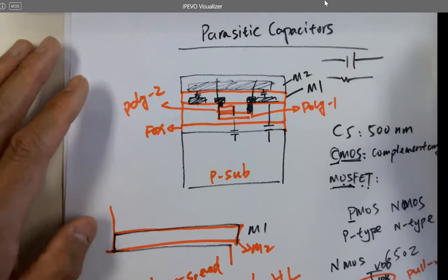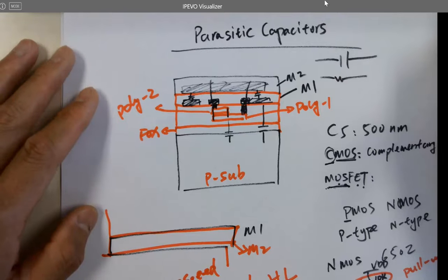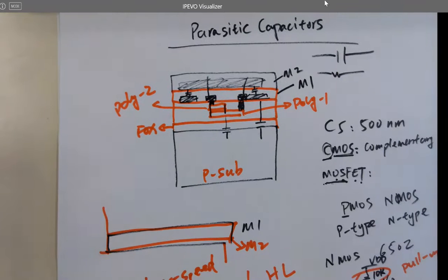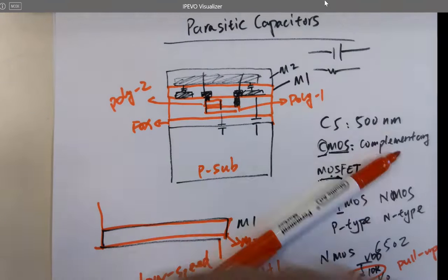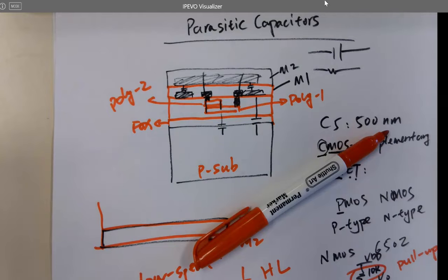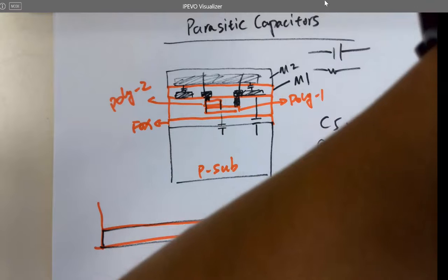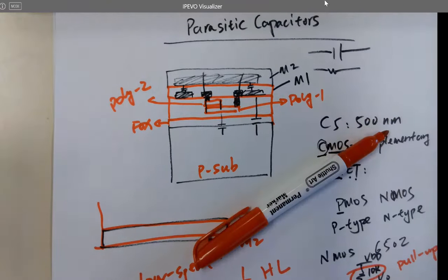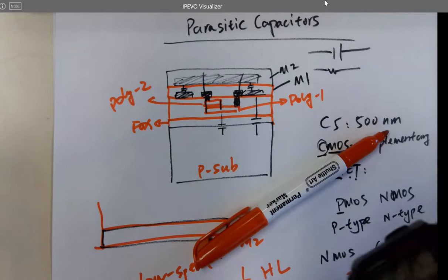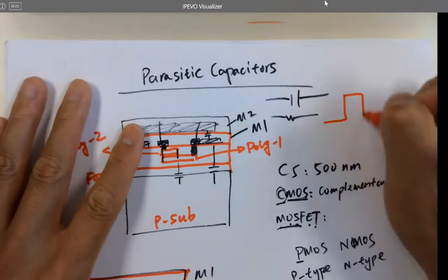Yeah. So for example, from one of the projects we are doing, from Kelvin's project, Kelvin Reese, for example, is probing temperature from the hot tubs in Puget Springs, right? And so the digital sensor, you want to convert the temperature data into digital as soon as possible because analog signal will introduce noises, right? So that's why you want that digital temperature sensor directly inside the hot tub. And then the signal is being converted into digital signal. So digital signal is just 0 and 1s, right?